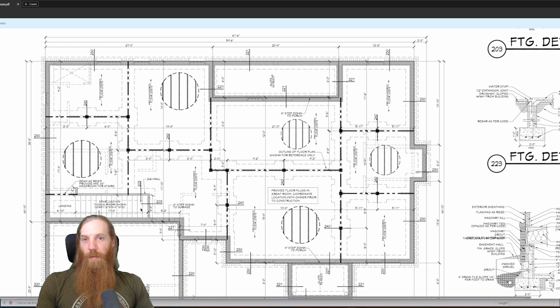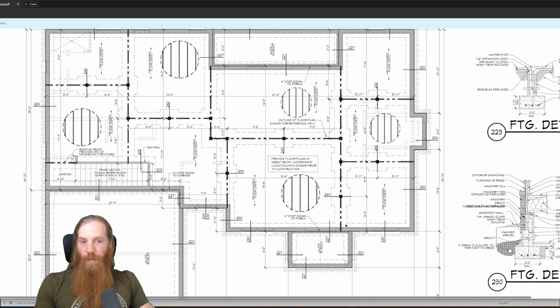I already mentioned this is going to be on a basement foundation. That basement foundation is going to be 5-6 feet at least below grade, right? Depending on how far I want to go down with the foundation. The garage foundation does not need to be 6 feet below grade. The footings in my area, frost depth is 36 inches. So that means my footings need to sit at 36 inches below grade. So I'm not going to do the garage foundation at the same depth as the house foundation. So I want to do the house first, and then I'm going to add the garage onto it.